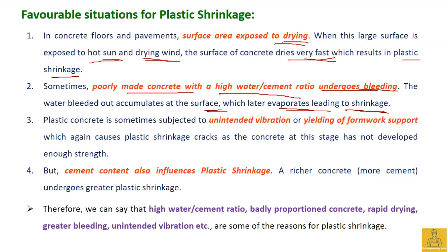Plastic concrete is sometimes subjected to unintended vibrations or yielding of formwork, which again causes plastic shrinkage cracks, as the concrete at this stage has not developed enough strength.